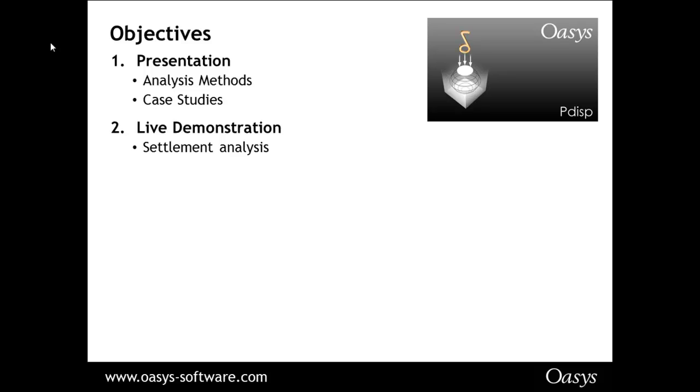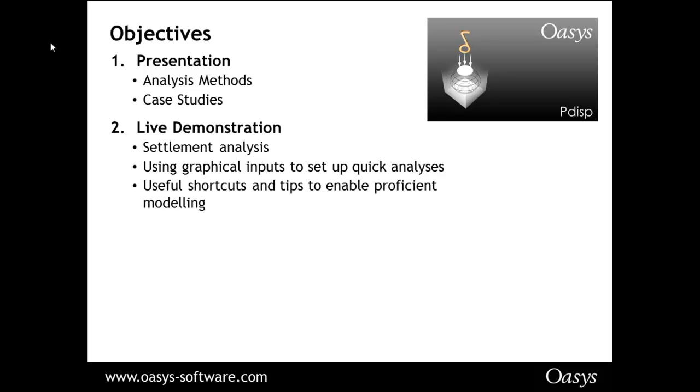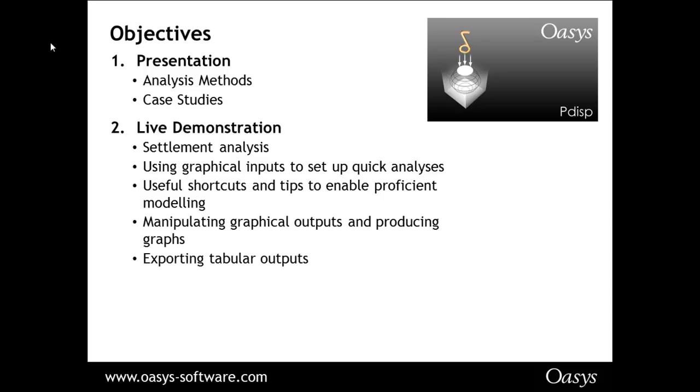But the main bulk of the presentation today is the live demonstration. So I'm going to carry out a basic settlement analysis and show you how to do it. We're going to be using graphical inputs as well to set up a very quick analysis. I'm going to introduce to you some useful shortcuts and tips to enable you to model very proficiently, very quickly. And also, one of the big strengths of Pdisp is its graphical outputs.